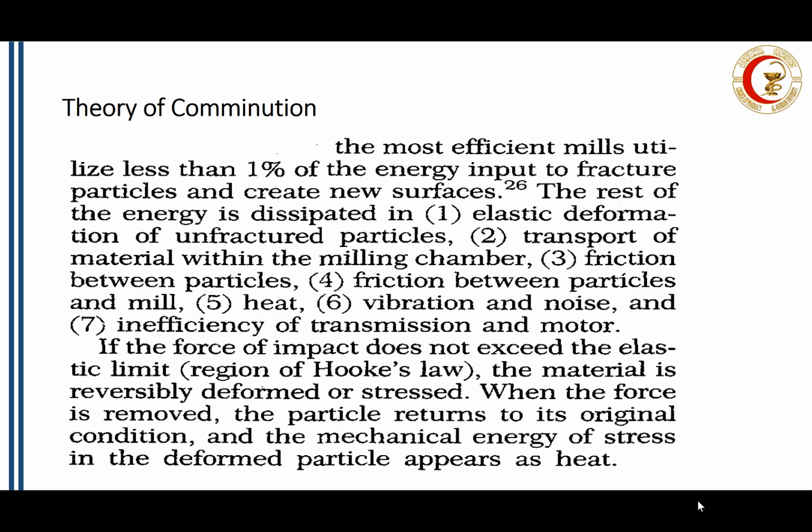The force that is required to break the particle is the force that exceeds the elastic limit, that is, the elastic deformation of the particles. So the most efficient mills utilize less than 1% of the energy consumed to fracture particles and create new surfaces. The rest of the energy is expended in the elastic deformation of unfractured particles.